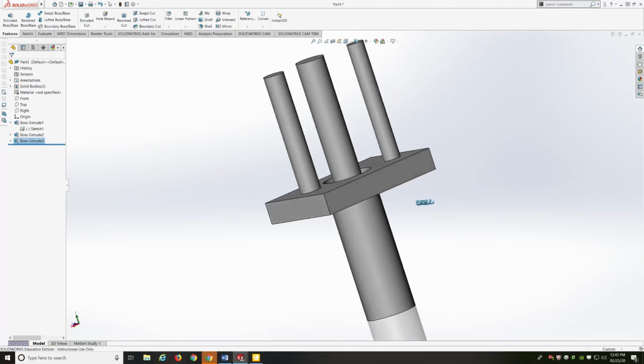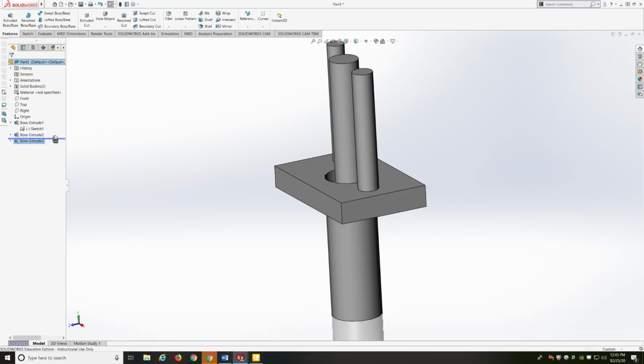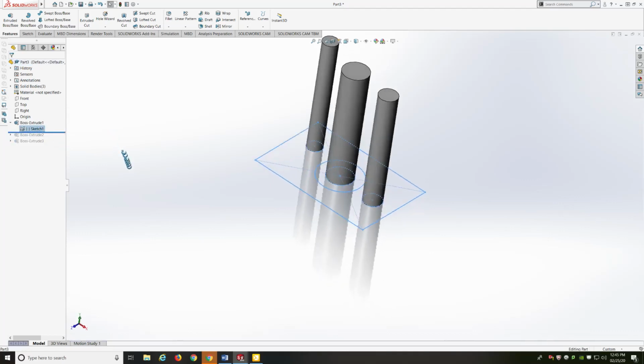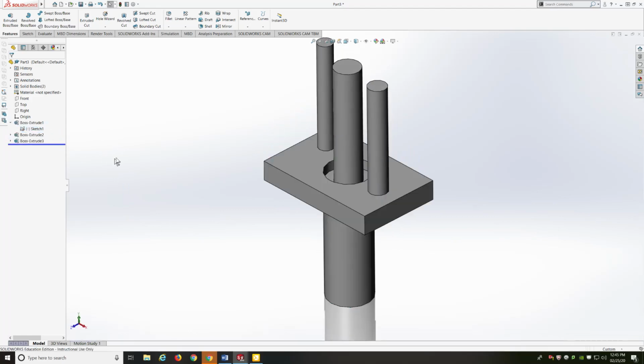Sometimes you can work with complex sketches. Again, we worked this with that sketch right there. I would prefer you to create simple sketches and fully define them. Add a feature. Create another simple sketch. Fully define it, add a feature. That's going to be an easier way to keep track of how you build things, and if there is a mistake, it's easy to find.